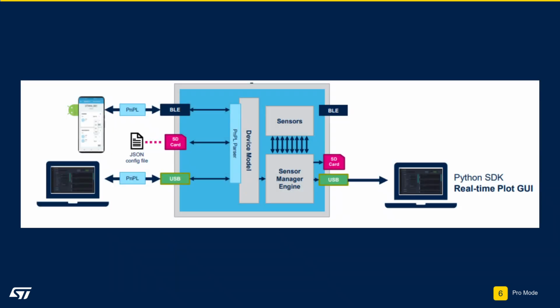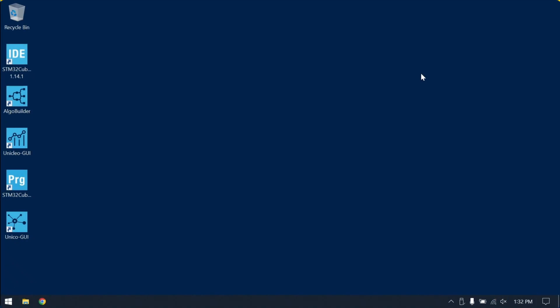The high-speed data log function pack provides a comprehensive solution allowing you to save data from any combination of sensors at up to their maximum sampling rates. We've already programmed the firmware to the board, and now we will use the Python scripts that come with the datalog2 function pack to capture and analyze sensor data.